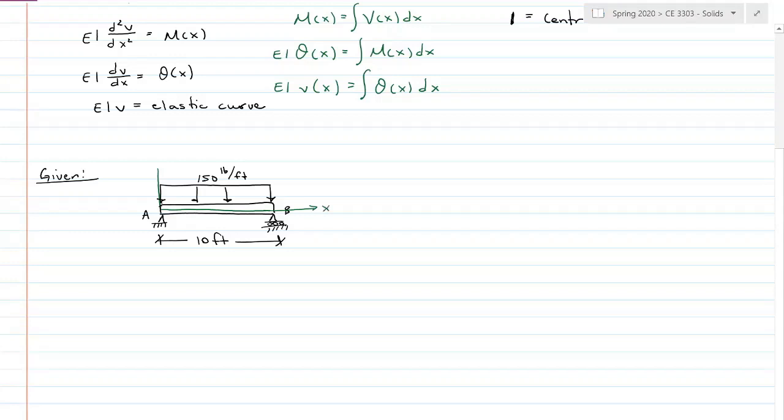All right, now if I'm talking about vertical deviation, I'm going to put some coordinates on here. X. And Hibbeler calls the Y direction, in this case, v, because vertical deviation is what we're talking about, so we're going to define the vertical direction. In this case, it's the up direction. I want to find the equations for slope and the elastic curve.